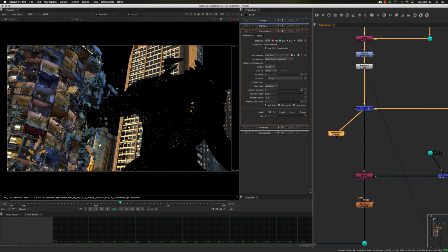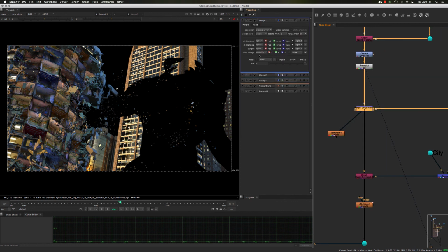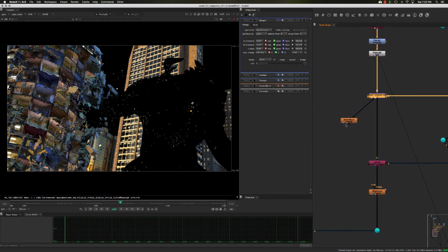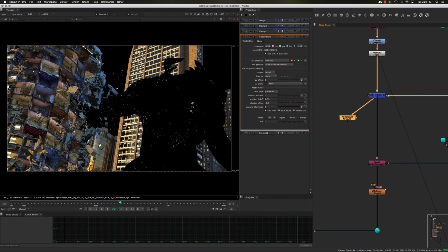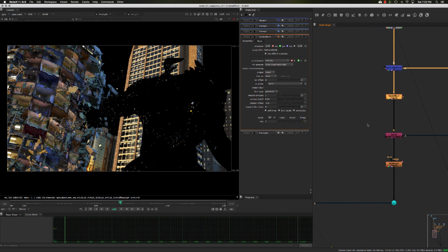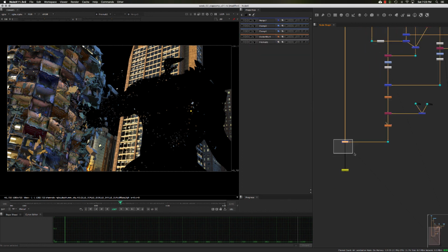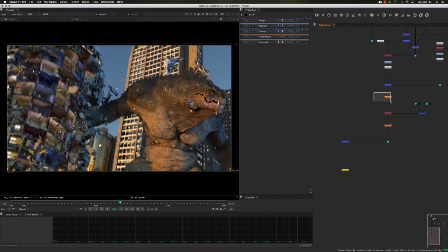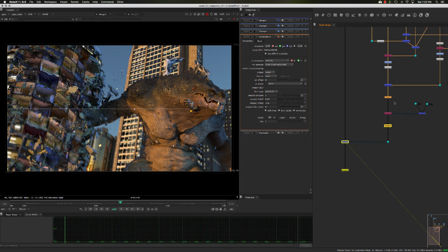And if you merge things cleanly using the also merge feature in the merge node and making sure you're getting your velocity pass coming through, you could vector blur everything together at once. So now we could just plug this into our stream, and if we look at our final result with everything over our background, we are getting nice motion blur on all the characters together.